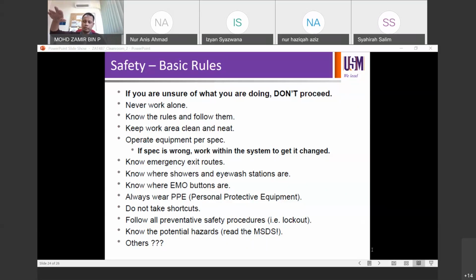Okay, but because the robot can move at high speed, X, Y, and Z, and also theta at high speed, I think they forgot to enable the interlock, and then somebody was doing maintenance on the robot, and then somebody accidentally ran the process, and the interlock was not enabled. So the system was actually running, and the robot was running, with the engineer or technician inside, and the robot hit him and broke his shoulder at high speed. So don't underestimate the importance of the interlock button.